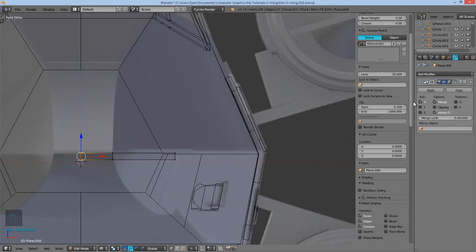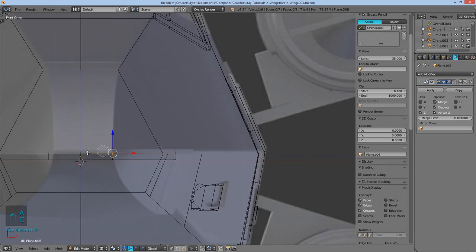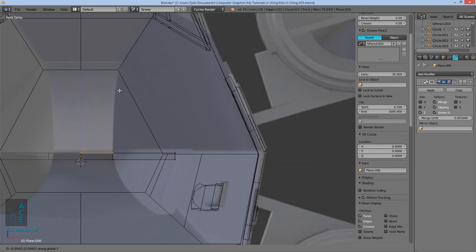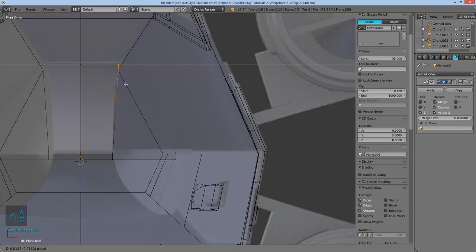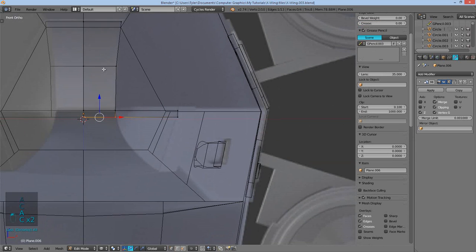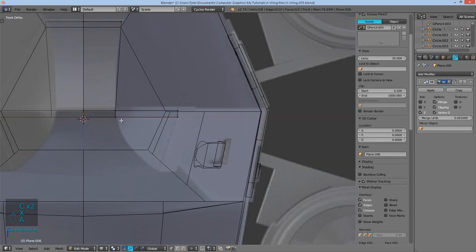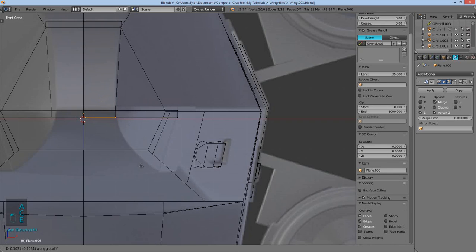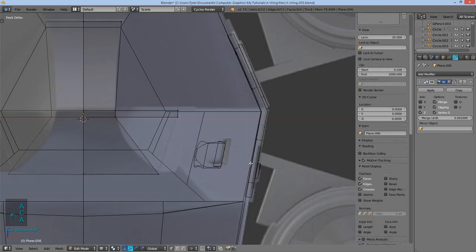The mirror modifier mirrored on the Z axis and will enable clipping. Then I'm going to extrude this on the Y axis, Z, sorry. Just like this, adding geometry and then smoothing it out. Actually, let's get that edge loop, it'll be easier to, yeah, you'll see in a second.